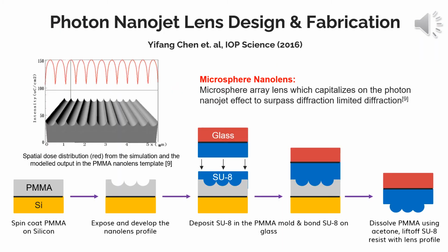Many large IC manufacturers are turning towards implementing deep or extreme UV lithography techniques to pattern their integrated circuits, though many smaller companies cannot afford the expensive equipment required to use this technology. Instead, there have been major research efforts for focusing beyond the diffraction limit, with one approach being using the photonic nanojet effect in dielectric microspheres.